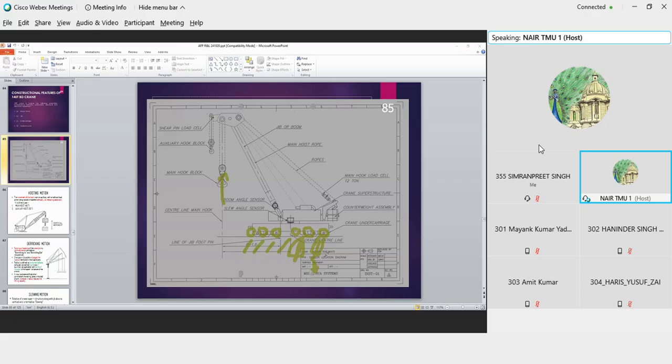Now, making of this prop is also a very difficult task, assuming that the accident has happened on a culvert. The accident has happened on black soil. The accident has happened where it is raining heavily. So you need to make a base for this prop, and that activity is called propping of the crane, or making the base of this prop.